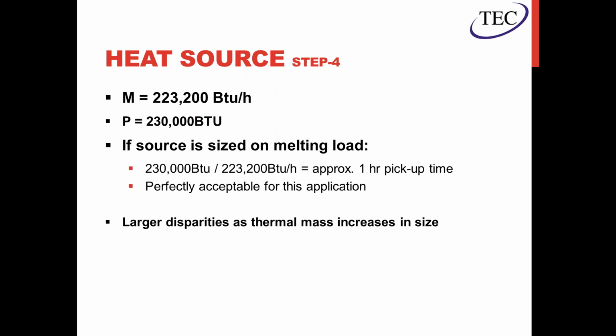So if we sized our heat source purely based on the melting load, in this situation with the pickup load, our pickup would be about an hour, since they're roughly the same size. It'd be slightly over an hour. And so for this application, since we're in just a simple sidewalk in a downtown area, allowing 1 hour for the slab to get up to full melting temperature is perfectly acceptable. When you get into larger thermal masses than 1,000 feet or different situations, it will make a difference.